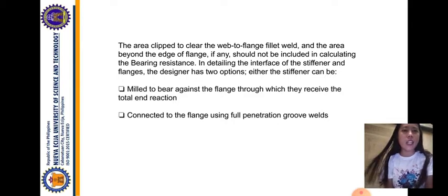In detailing the interface of the stiffener and flanges, the designer has two options. Either the stiffener can be: 1. milled to bear against the flange through which they receive the total end reaction, or 2. connected to the flange using full penetration groove welds.